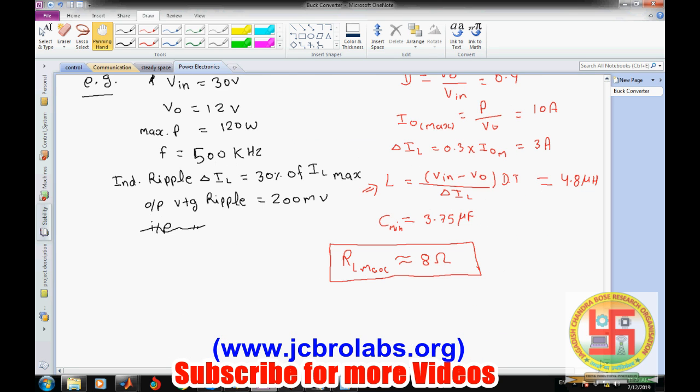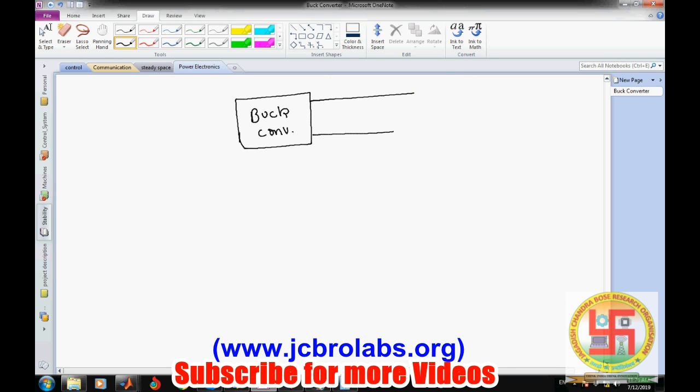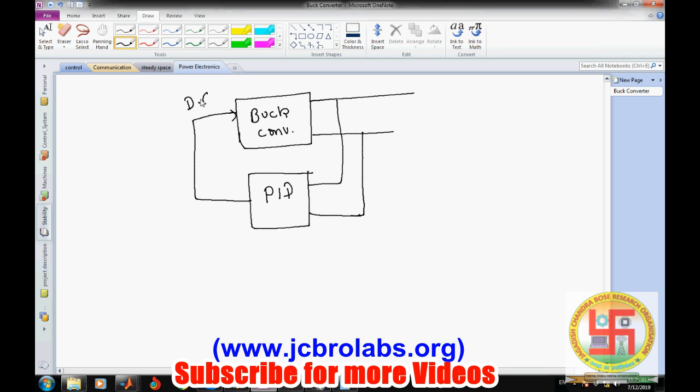So one question is obvious to come into your mind. We can apply, let's say, a controller in order to get a constant voltage, and how can we do that? Let's say this is our buck converter, and this is the output voltage. What we can do is feed this output voltage to a PI controller, or let's say to a PID, and from here the output of this PID goes to the duty cycle of this buck converter.